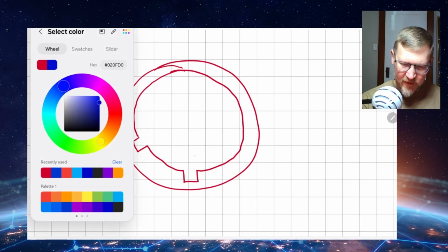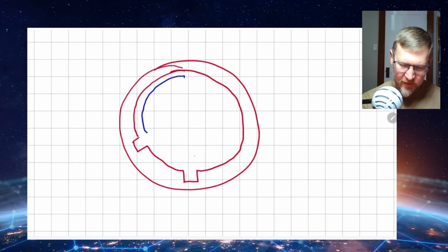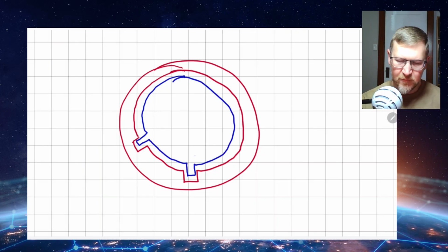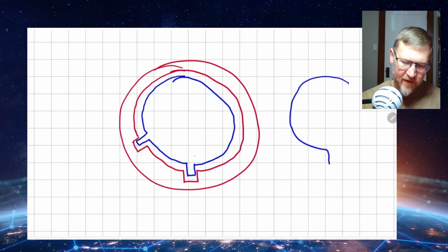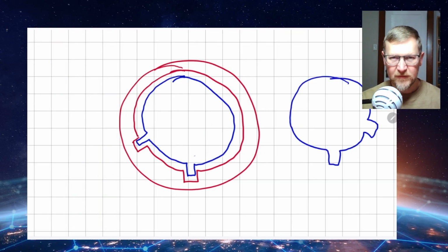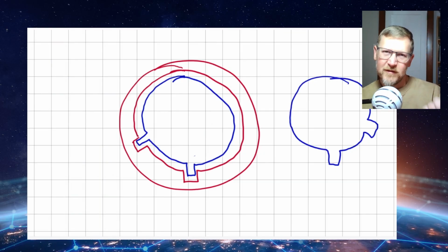Basically, your connectors are not going to be interchangeable. So even though they may be the same size, unless your connector has the right key feature, it will not interface. In this case, it's got two keying features on it, and your mating connector has to have the same matchup. If I had another connector off to the side, which perhaps had the same feature on one side but not on the other, that would not interface with this connector, and so that would prevent someone from physically installing it in the wrong spot.